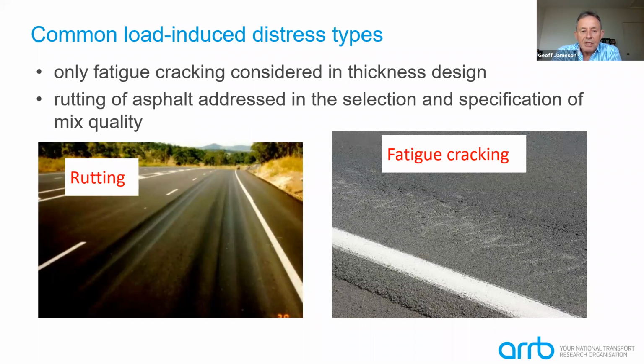Rutting, which is the other mode of distress of asphalt layers, is not addressed in our design model, but is handled through appropriate mix design and selecting material based on its mix design characteristics, the volumetrics, possibly wheel tracker testing of the material,